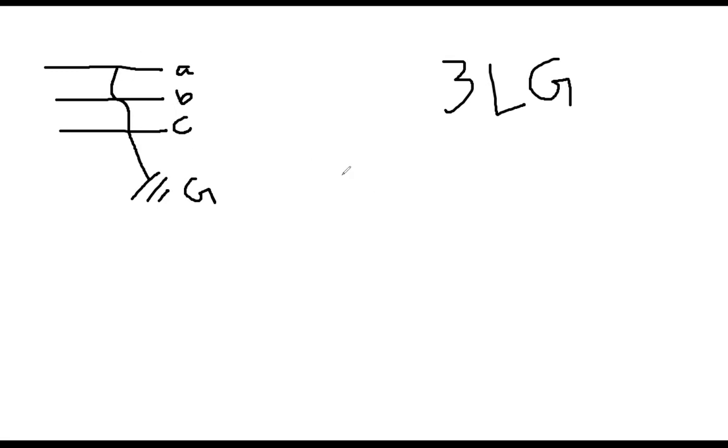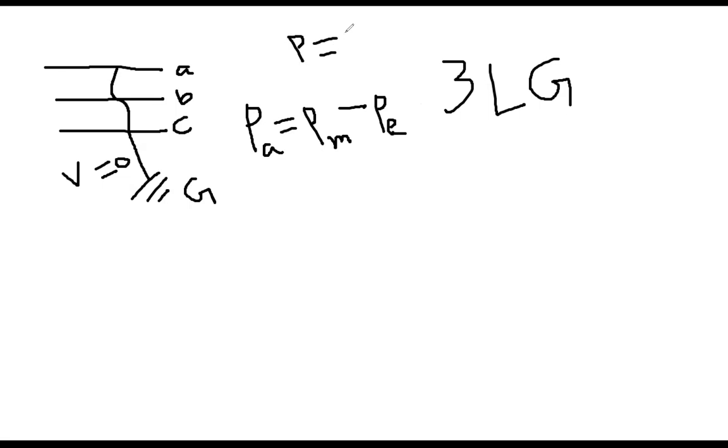So if this is the situation, then again, if you go back to that equation, what will happen? Phi equal to Pm minus P. Under this situation, because this is a short circuit, the voltage is 0. So what is your P? P means the multiplication of voltage and current. Whatever the power factor, the first thing is the multiplication of voltage and current. So it is going to 0 or close to 0. Consequently, your power value, P value, will be 0.